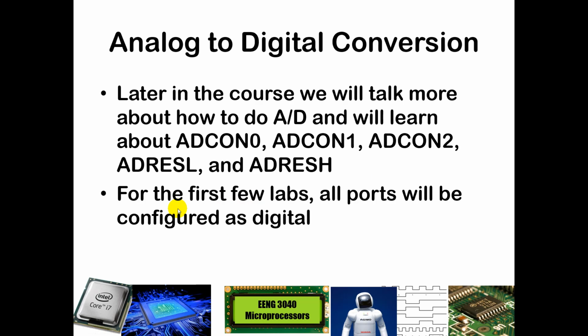We'll talk later in the course. We'll have a whole lecture on analog to digital conversion. I just want you to be aware that there are specific registers associated with that. ADCON0 and ADCON1 are used for the analog to digital configuration, and so is ADCON2, and then the results are actually stored across two registers, ADRESL and ADRESH.